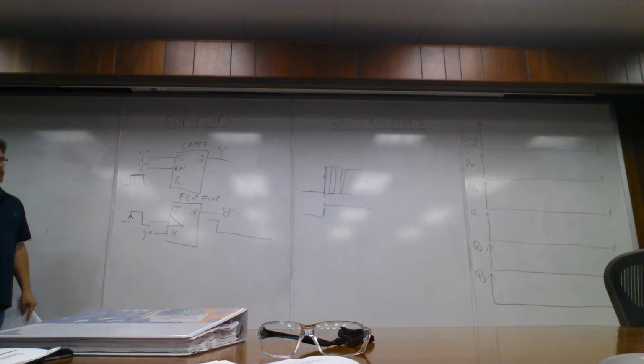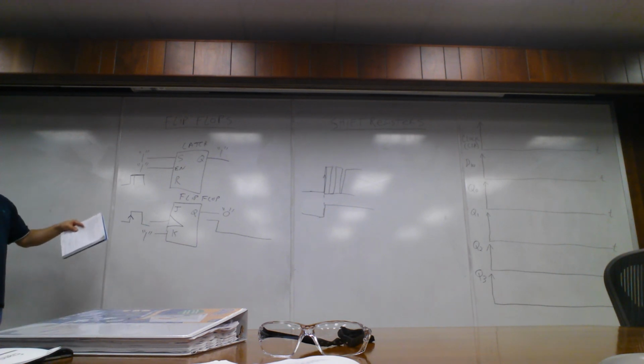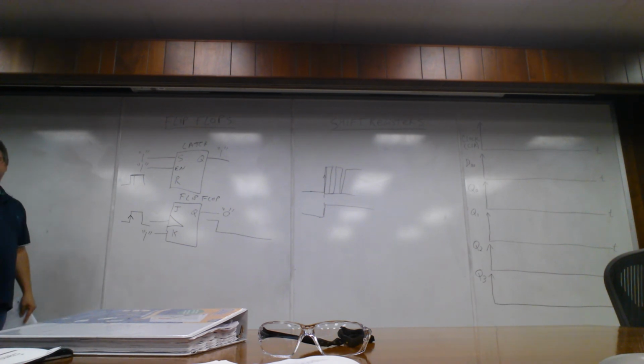Frequency division is one aspect of it, which Damien's going to go into, using JK flip-flops for toggle operation. Sometimes they call them toggle flip-flops, and they're just combinations of Ds and JKs. A D flip-flop is nothing more than a JK with an inverter. And the JK is basically the primary system element. So with that, I'll let Damien. You want to go through the JK?